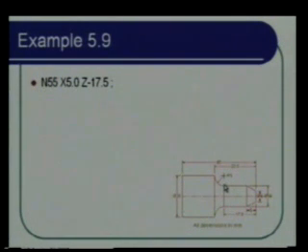Notice the Z values are all specified negative because your datum is located at the end point. Always we will be using the Z datum as the end point of the workpiece, so that all Z negatives will be taking the tool inside the workpiece.